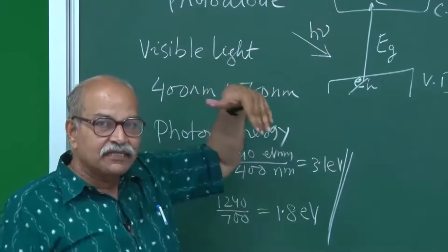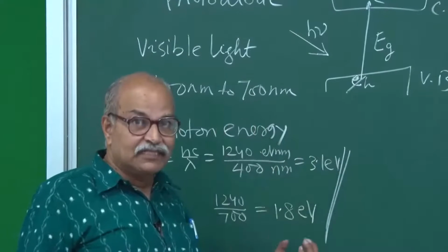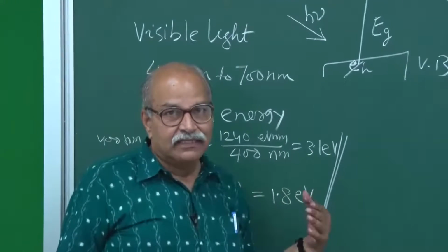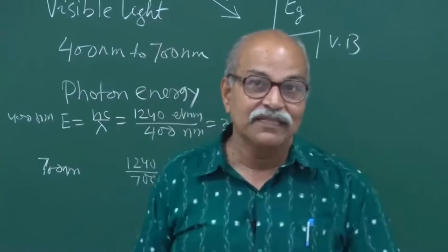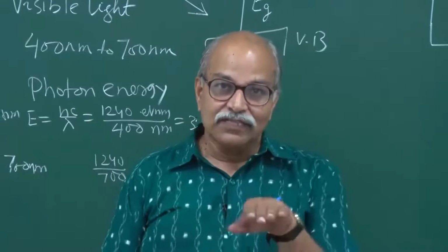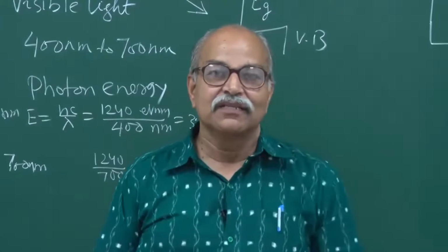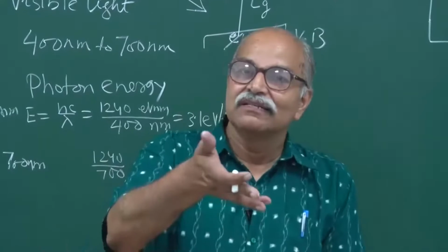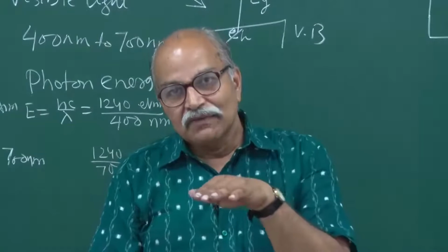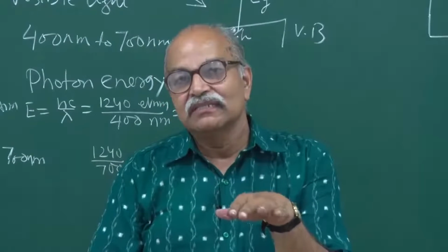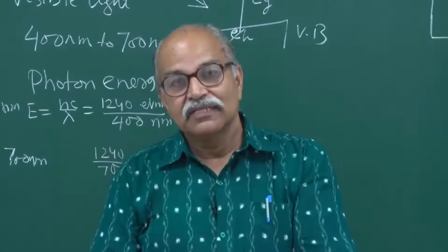there is a chance. So, photodetectors are made with this idea, or if it is to be used in this fashion, we call it a photodetector, and then light has to reach this depletion region. So, that has to be taken care of in fabricating it. The rectifying diode that I showed you is all covered in blackish material, so light will not reach the depletion region. So, here it is constructed so that you have a transparent cap on this junction, so that light from outside can go and fall on this material.